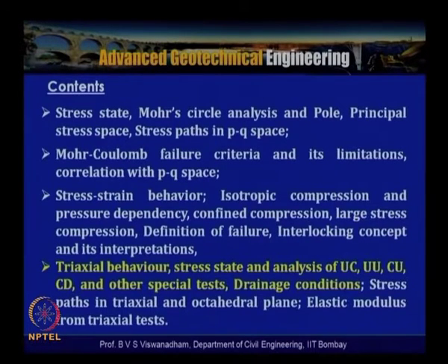So we have several methods for determining shear strength in the laboratory. Predominantly they are the direct shear test and the triaxial compression test, and then there are the simple shear test and the plane strain triaxial test. Like that we have several classes of tests which can be done in the laboratory for determining the shear strength parameters of the soils under consideration, both in disturbed or undisturbed conditions or for remolded conditions.